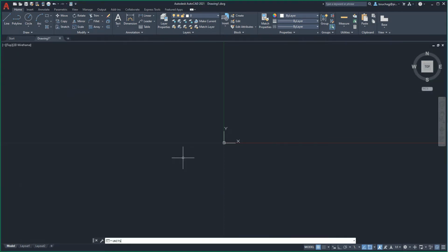Before we begin drawing, we first want to verify the units of measure currently set to be used in this drawing. As noted in the previous video, inspecting the units settings of drawings we receive from other sources is recommended. When typing a command, it is not typically necessary to proactively activate the text cursor in the command line. The software simply interprets the typing process as the user's intent to communicate and input a command, and the text the user types will automatically display in the command line.